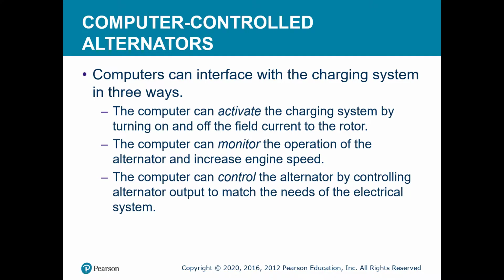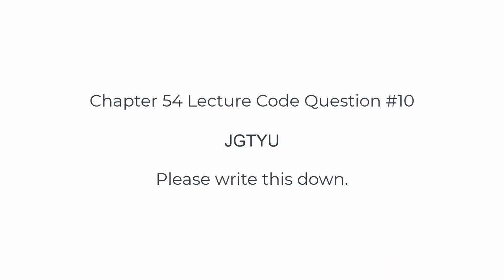Some of the other neat stuff in part of the control or the logic that the computers use, the theory of operation, is they look at temperature. So a computer, a PCM, BCM module, whatever, would use the intake air temperature to determine how to charge back the battery or how to operate the system.